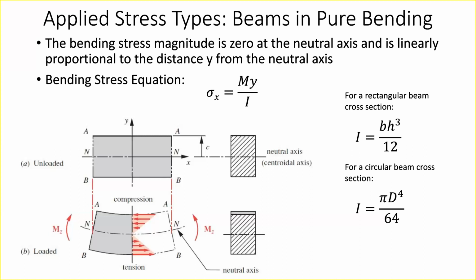And for example, going back to that workflow in terms of a sanity check: if I'm designing a part and I have an idea of how much moment load I expect on it, I can relatively easily come up with an approximation for the cross-sectional area. So if I need to determine how large to make this part or what material to make it from, I can easily solve for the peak stress at the outside of the part, since when you bend it, all of the peak stresses happen on the bottom or the top. Based on that peak stress, I get a sanity check: have I made my part large enough to react this load?